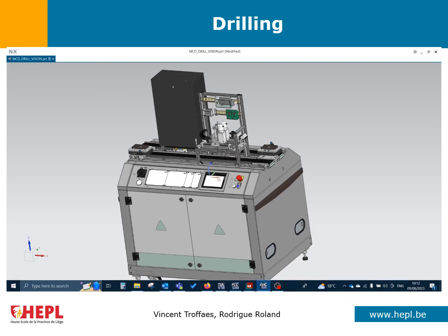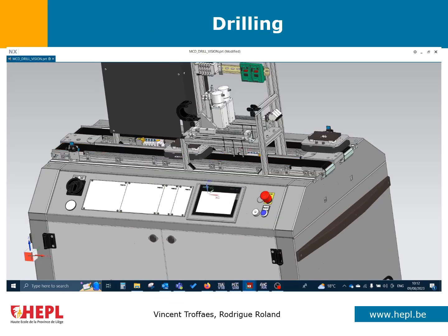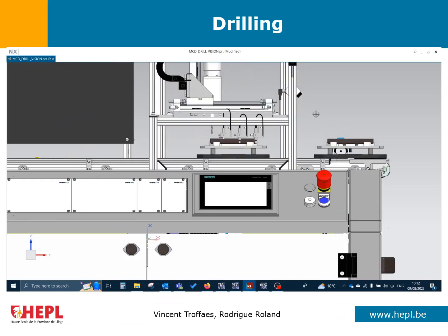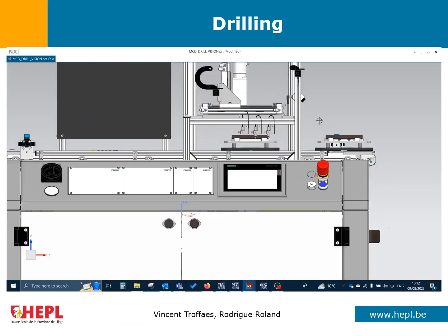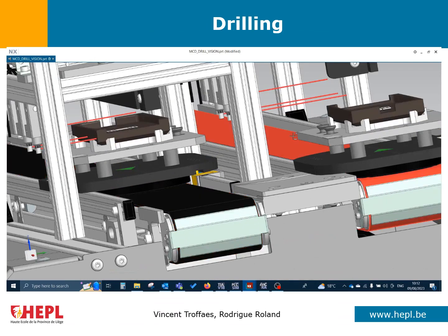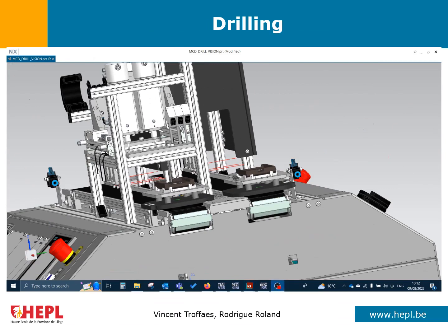The drill application itself was one of the simplest. This only contains pneumatic movement on the X and the Z axis, and then we have the drills. The pneumatic movements are realized with sliding joints, and the drill rotations were realized with cylindrical joints. Collision sensors were used to detect the parts, and limit sensors were used to detect the position limits of the axis.